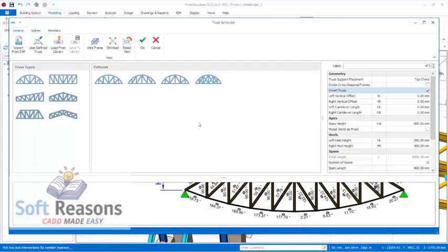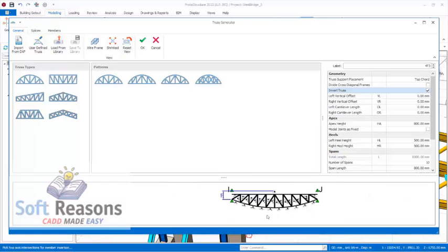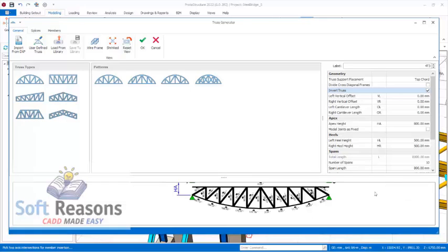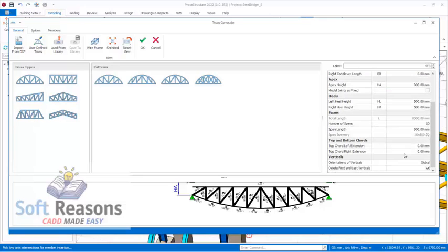Having gotten this, we need to move this whole thing to the user defined truss options. What we have to do before then is some little settings here, because any changes you make to these trusses, like user defined changes, you won't be able to access the geometry provisions.